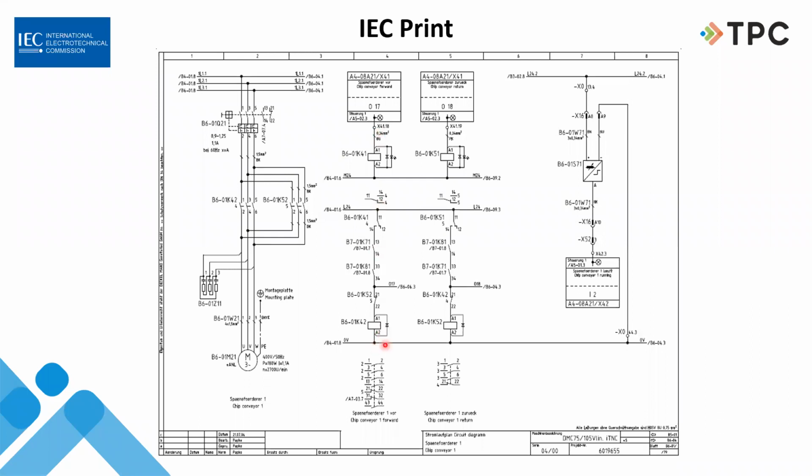And what we know by looking down here is that this is a contactor with auxiliaries. Why? Because these are all single-digit contact numbers, and these are all double-digit numbers. So we know we're doing both on this. When it functions, it's going to close some main contactors to, in this case, turn this motor on. And it's also going to have some interlocks, because what we're looking at here is a forward and reversing contactor. And so we're going to have contacts that interlock it.